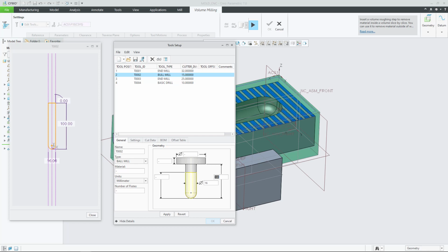The functional length is 200mm, so I think it would be more than acceptable to put half of that length out of the end of the holder. It still leaves us 100mm to actually clamp inside the holder. As I've already said, common types of holders are BT40.